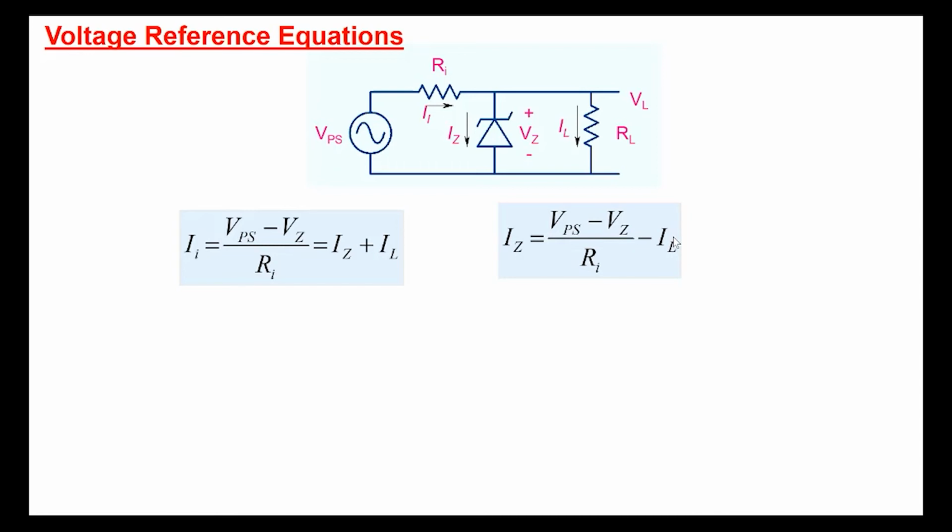And so now the issue in using a Zener diode is we have to make sure that the Zener diode is operating in the Zener mode, in that steep IV characteristics or in the breakdown mode. And further we have to make sure that the current through the Zener diode doesn't exceed its maximum current rating, or the power dissipation in the Zener diode doesn't become excessive.